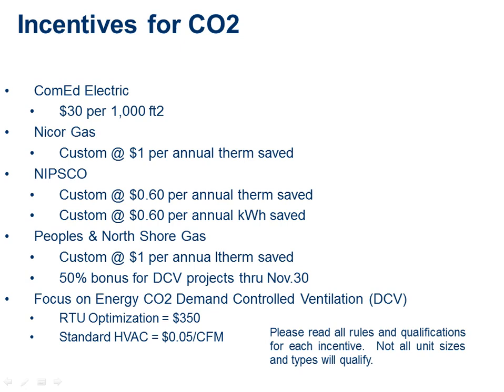I'll show you that specifically, but having plus or minus 50 parts per million is pretty much the norm for a decent CO2 sensor. But when you're talking about 1,200 parts per million or something, that's not horrible. The other thing is we're tracking the difference between inside and outside, so we're really more concerned with the difference and less concerned with the actual level. It says there must be better options for DCV. There's probably not. I'll talk about a couple other options in a little bit, but this is probably the best way to do it, and I'll explain why.